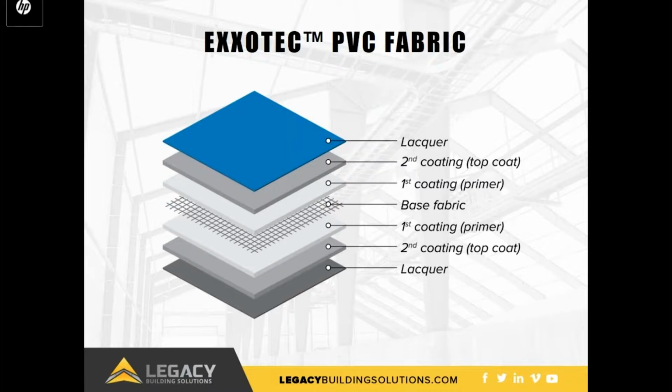The final layer of the fabric is a lacquer. The clear lacquer has 2 primary roles: to keep plasticizers within the PVC from coming out, and to provide a smooth, self-cleaning finish. Many PVC fabrics are also flame retardant in accordance to NFPA 701 and the California Fire Marshals. The picture shows EXXOTEC, which is a PVC fabric exclusive to Legacy.